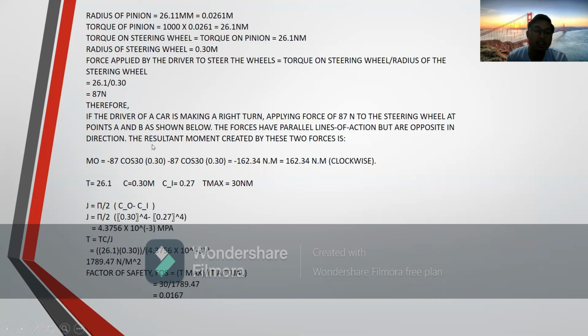The relative moment created by these two forces is the moment negative 87 cos 30 times 0.30 minus 87 cos 30 times 0.30, which equals negative 162.34 Newton meter.